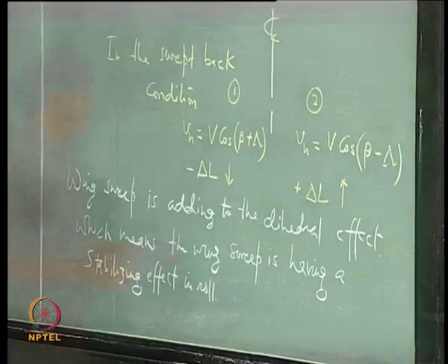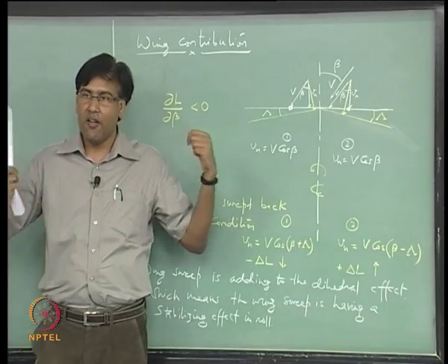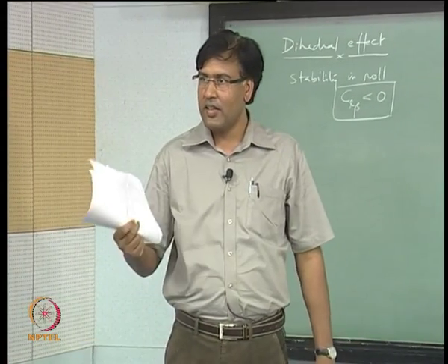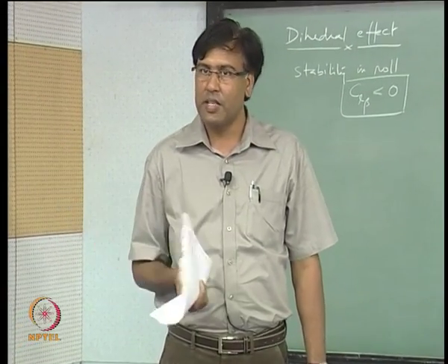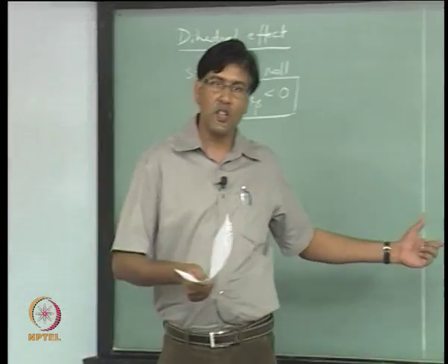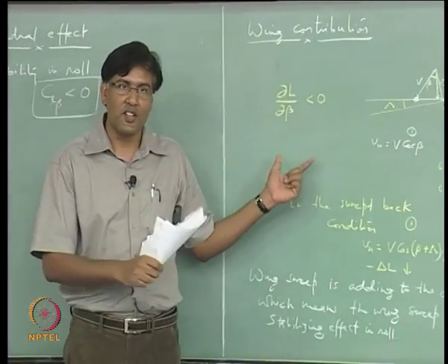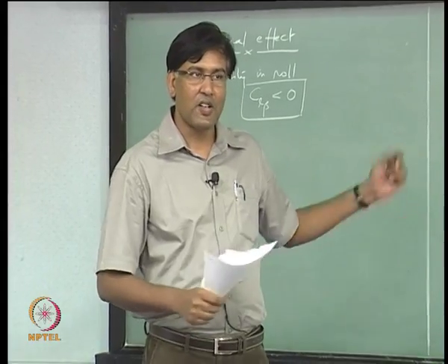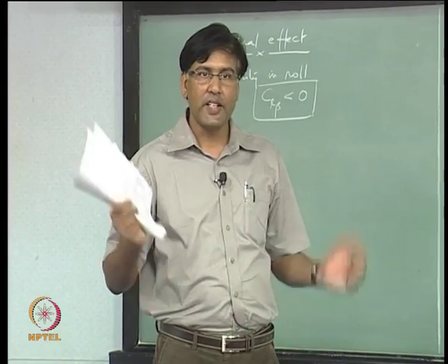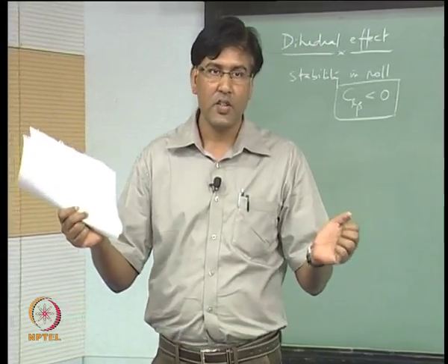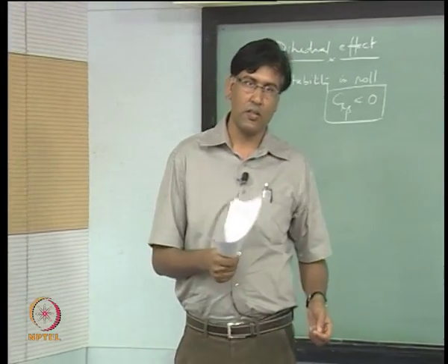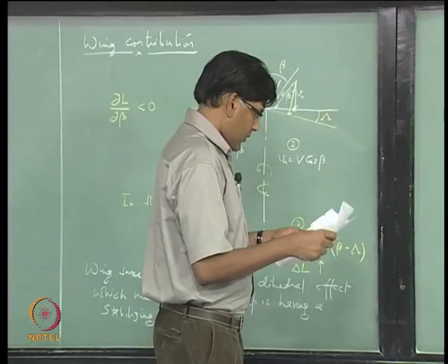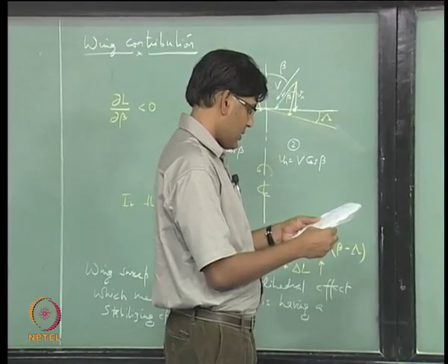All right. For the same reason, when you have wings swept forward, the effect is going to be destabilizing, right. That is the homework. Okay. So, you should try that at home and figure that out yourself. So, wings swept forward is going to have a destabilizing effect on roll.